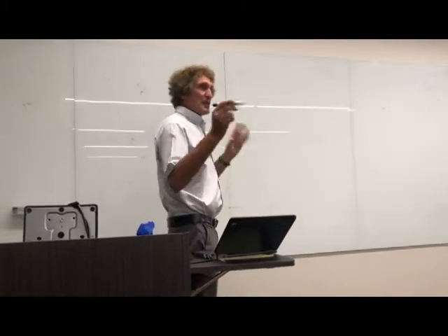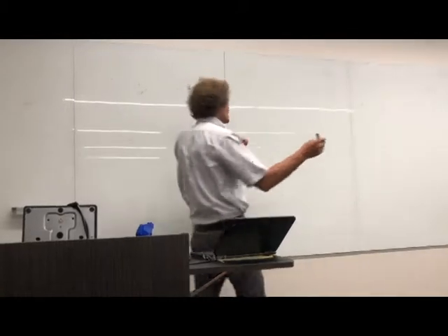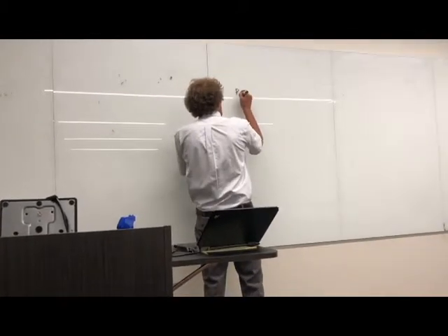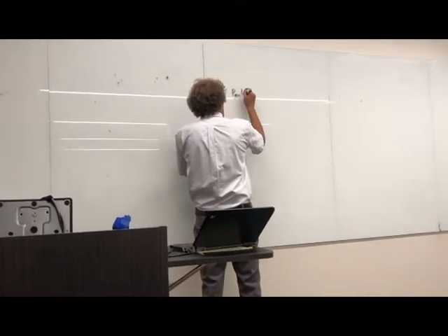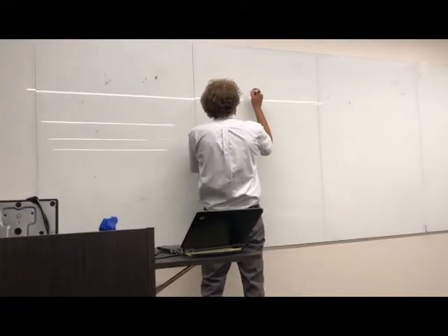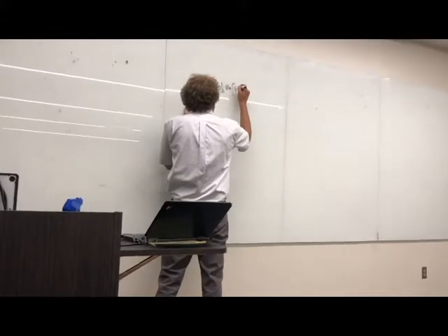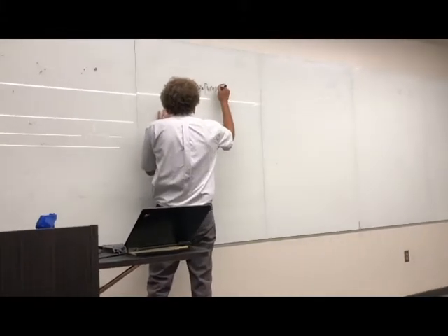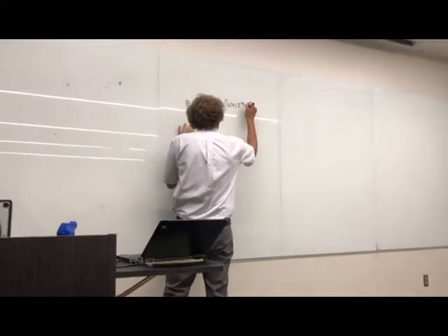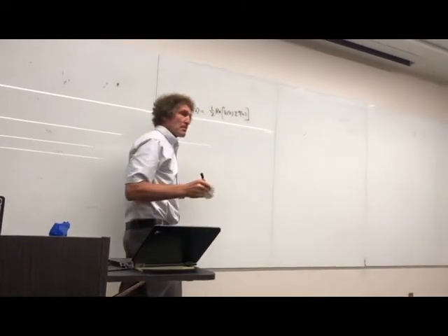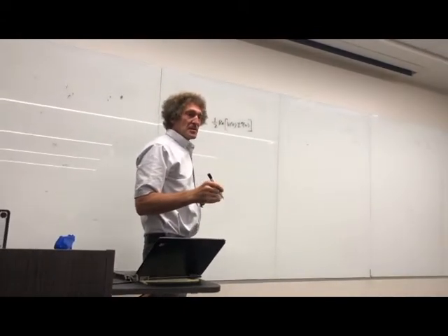Something else, now I'm going to relate this to what we left off last time. Do y'all remember when I did the power formula, I said the average power flowing in a transmission line was equal to 1/2 the real part of really the voltage in the transmission line times the current conjugated in the transmission line. Do you remember that from last time?